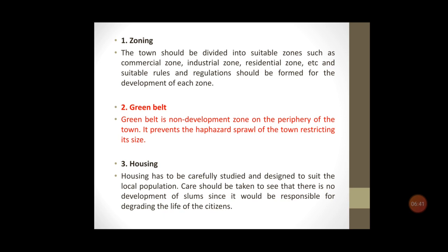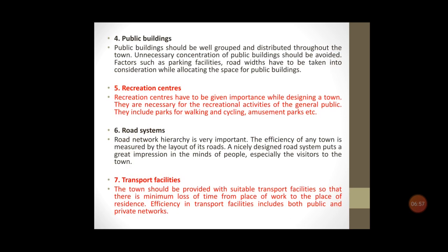Third is housing. Housing has to be carefully studied and designed to suit the local population. Care should be taken to see that there is no development of slums, since it would be responsible for degrading the life of the citizens. Public buildings. Public buildings should be well grouped and distributed throughout the town. Unnecessary concentration of public buildings should be avoided. Factors such as parking facilities and road widths have to be taken into consideration while allocating the space for public buildings.